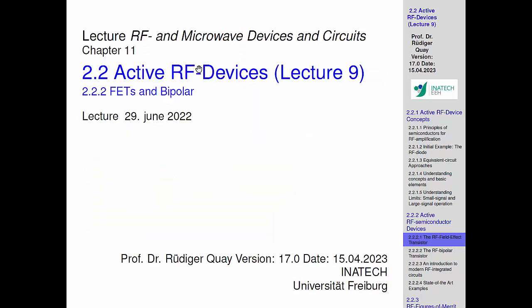Okay, I'd like to stop here. What I would like to do next time is to get a relative comparison. I was now heavily bashing the bipolar idea in terms of speed, but that's a bit unfair because the FET is a very good combination: we have this high forward current and we can easily reduce the capacitances when we do this nice lithography.